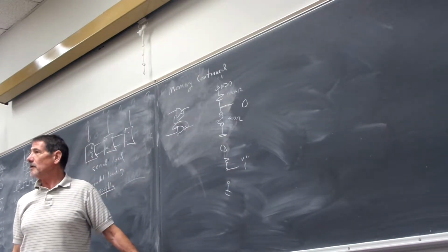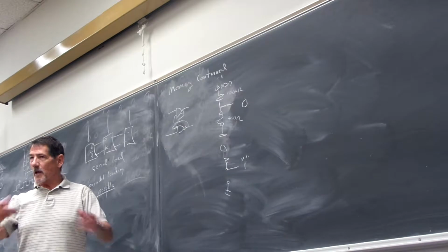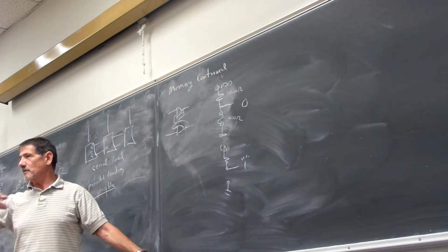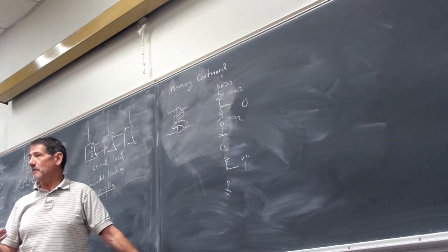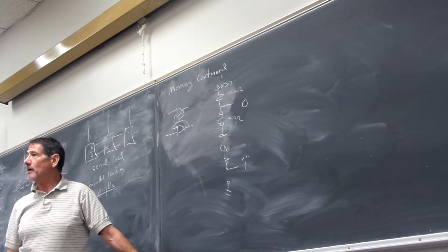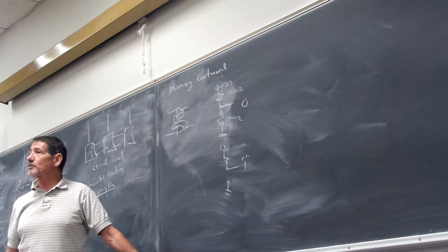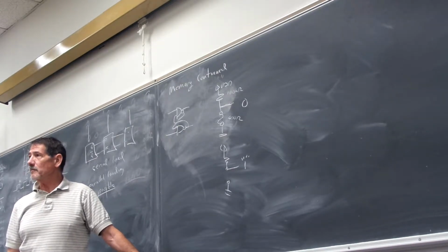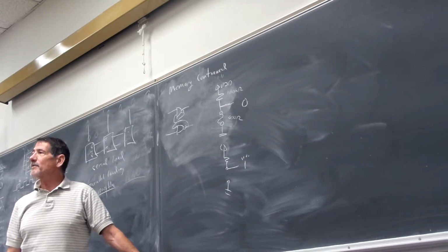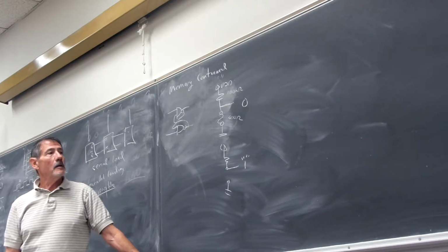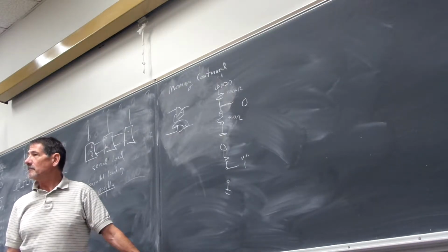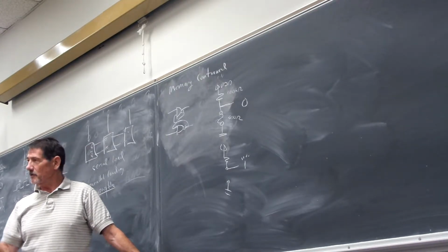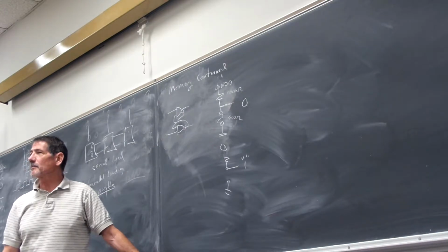Is that okay? So at the factory, you could have a gazillion of these guys, and now how you read the information, we haven't talked about. But here's a cell that we could store information into. Okay. So what happens if you write a 1 there? Are you ever going to be able to write a 0? The answer is no. There's no little switch in there that you can toggle it back.